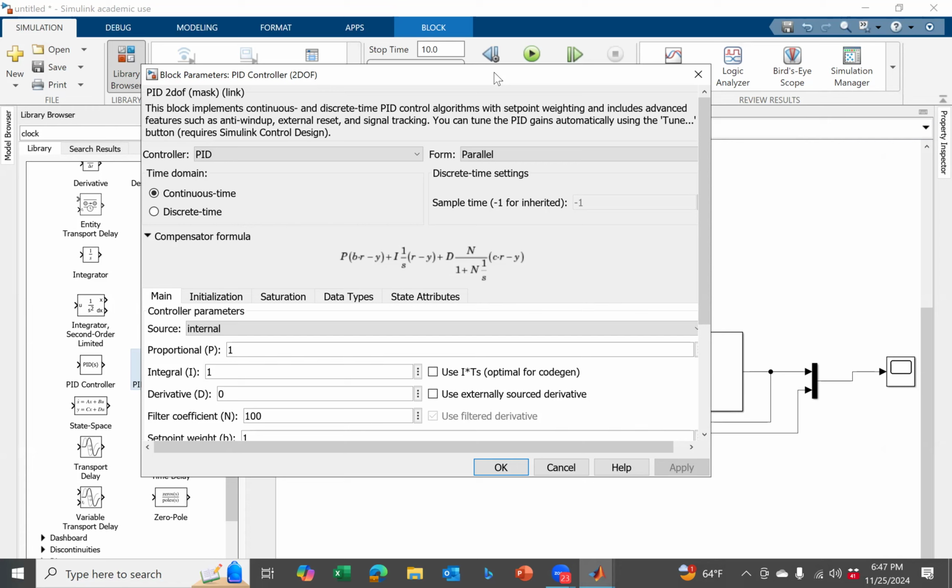So here you have two constants. One constant is B and the other constant is C. B is scaling the input which is going into the proportional control, and C is amplifying the input that is going into the derivative control. Everyone understood this? Why is this jugglery?